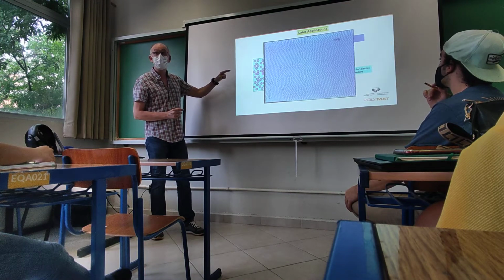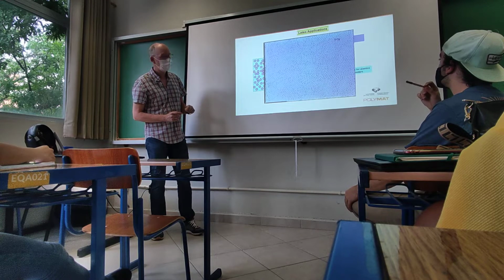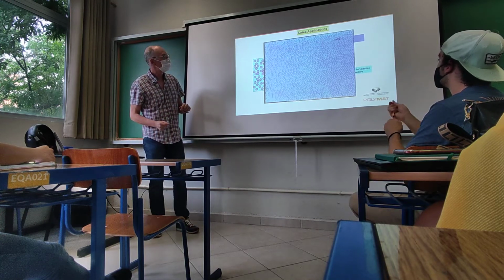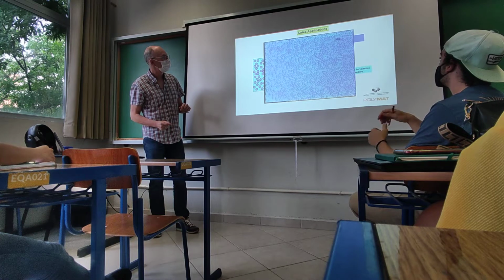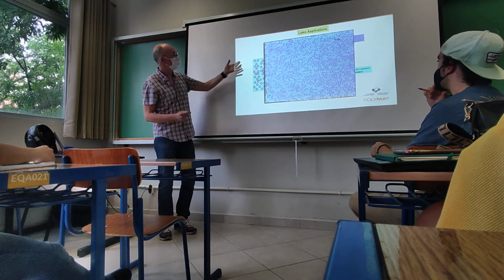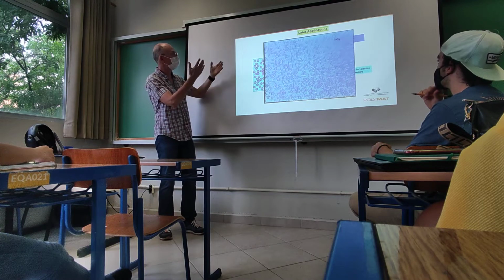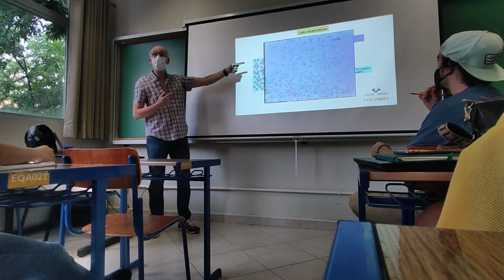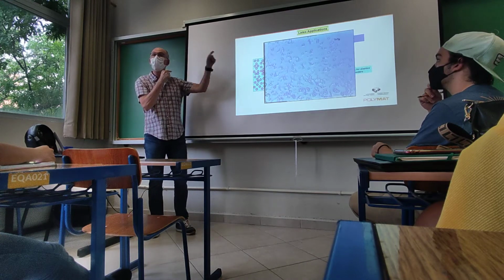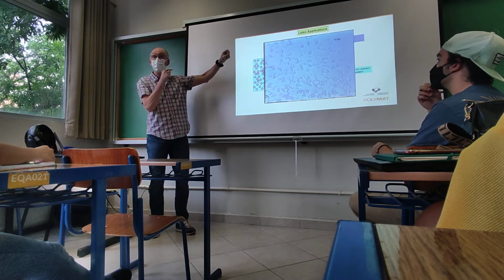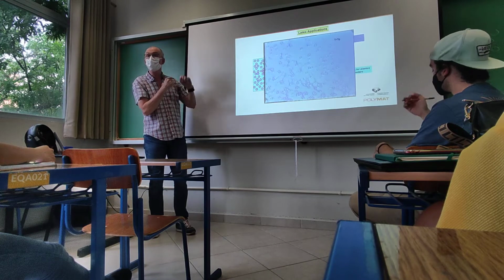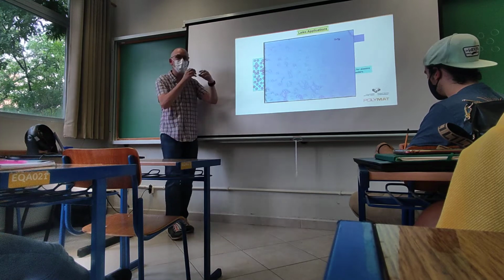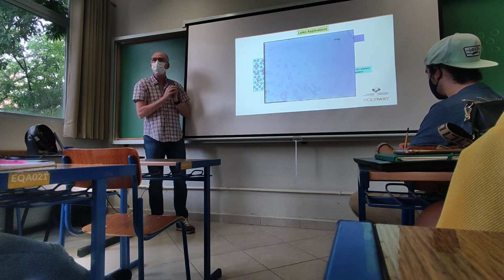Now the coalescence will be shown. So you see, the particles are losing their identity. They are becoming a single film, but to be able to do this, the temperature should be higher than the temperature of the glass transition of the polymer in the particles. Okay? And you will end up with a coherent film where all the structure has disappeared. Okay?